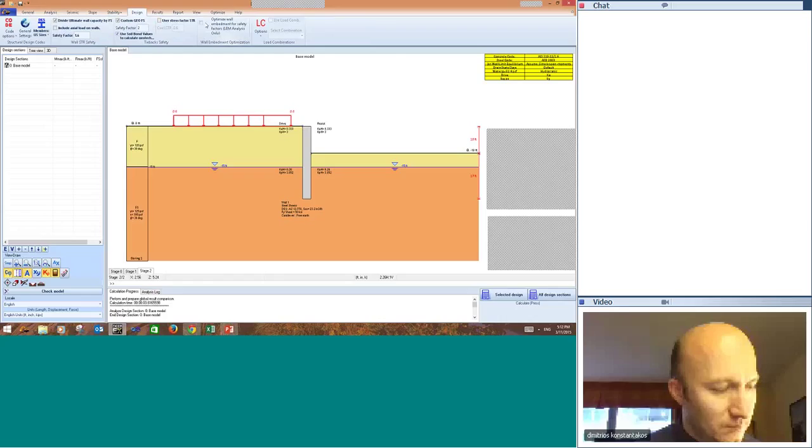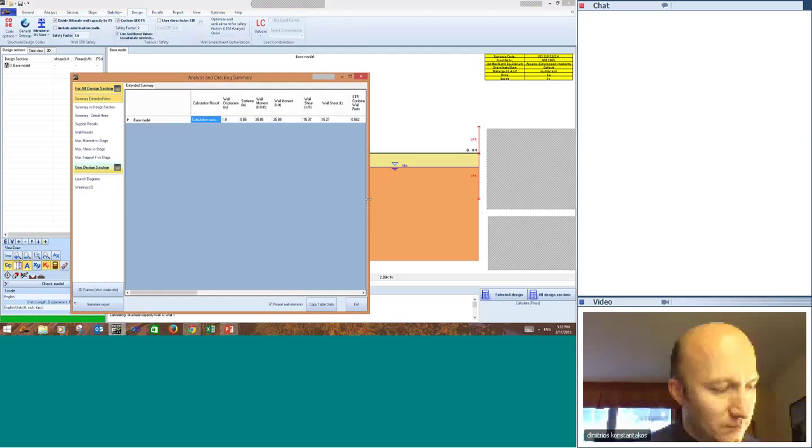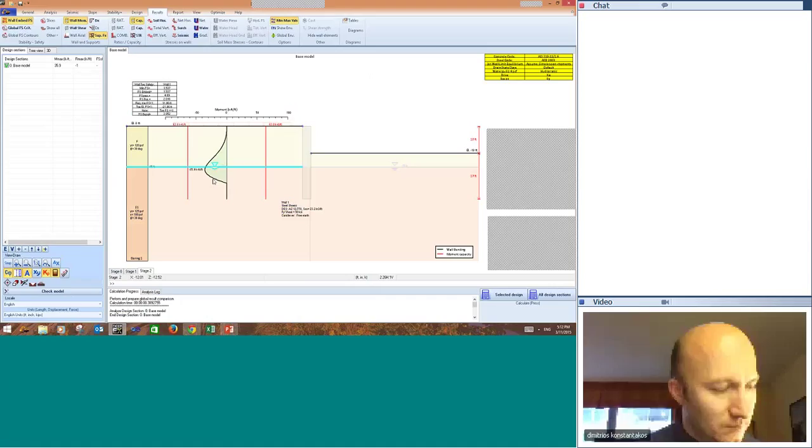I went to the design tab. I've taken out the optimization for the wall embedment. We run the analysis, and we're seeing that the stress checks are more reasonable and much closer to the bending moment. So this, in essence, is our first simple optimization case. Now, what we'll do is we'll build up on this, and we'll actually add the tieback.